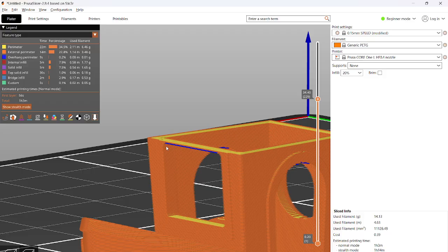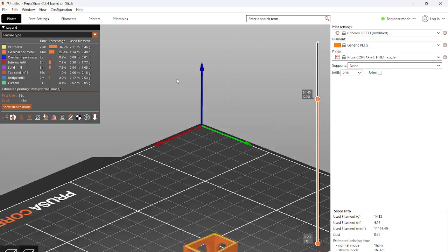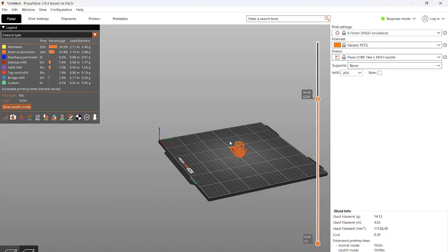But for the most part, it will make your part a little bit worse, especially when you're printing at really large scales. Like when I was printing a really, really large cylinder, you could see the individual triangles on each of the faces around the circle, right? Because it's an approximation instead of being exact. So it'll have slight defects. So I personally prefer the step file over the STL file.